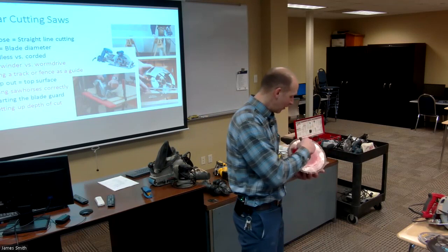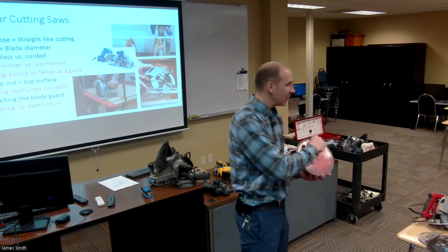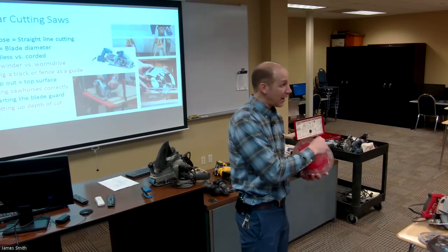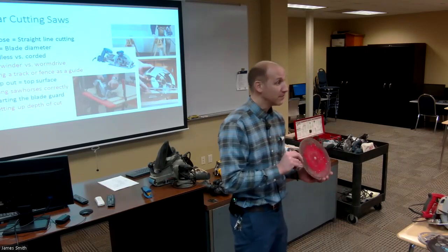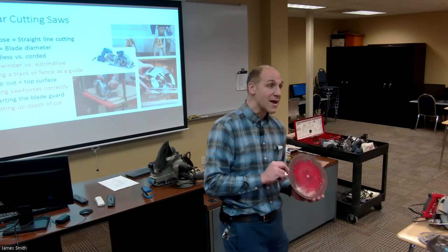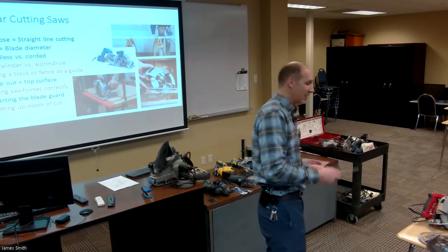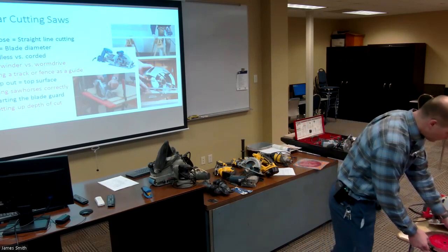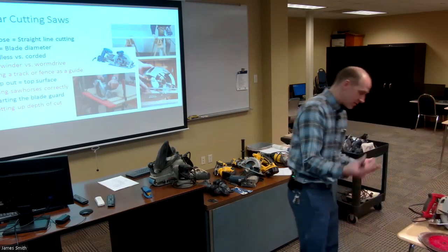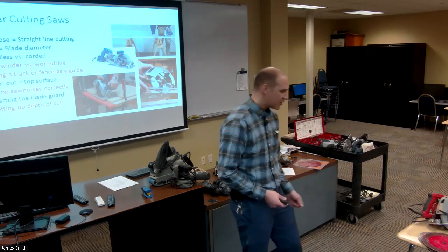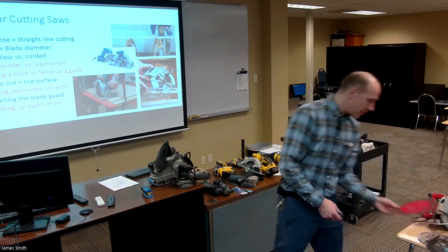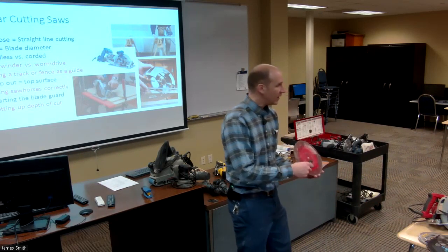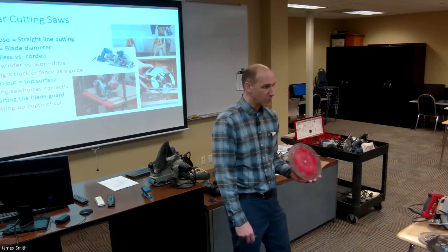But eventually the blades do wear out, and the sharpener will sharpen it one last time, and he'll put on there using an engraving tool, NWS, not worth sharpening. Basically meaning, use it this last time, don't send it back, because it's not quite running true anymore. And the other thing too is, if you're really abusing these things, eventually these little carbide teeth will come loose and they'll break off.